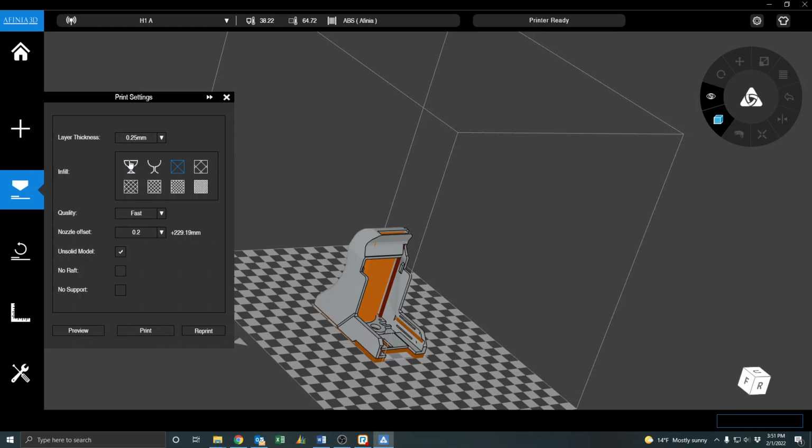Infill. This is going to be a shell infill, so basically like a chocolate Easter bunny. Nothing on the inside, only on the outside. And then this is just vertical walls. So you're really never going to need to print this at all. It's just there. But these are the important ones. We have 13%, 15%, and it goes all the way up to a 99% infill. And it does it by doing this cross-hatching pattern inside of the model. I recommend you stick at 13% or 15%.